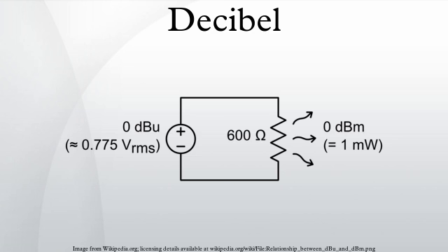dBr, decibel relative: simply a relative difference from something else, which is made apparent in context. The difference of a filter's response to nominal levels, for instance. dBrn, decibel above reference noise. See also dBrnC. dBrnC represents an audio level measurement, typically in a telephone circuit, relative to the circuit noise level, with the measurement of this level frequency weighted by a standard C-message weighting filter.